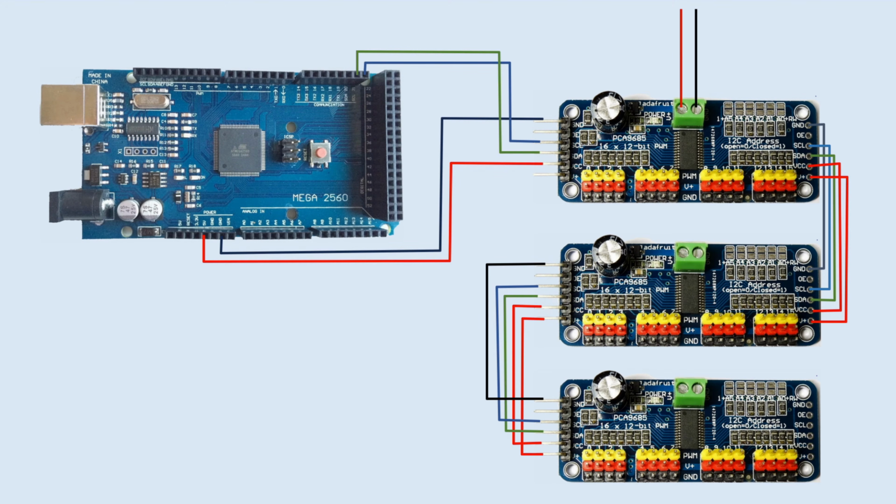All right, as far as setting it up, there's 4 wires that come off of the Mega to control the PCA9685. And you can daisy chain these together and add multiple boards, as we mentioned. Doing so is just a matter of running the wires from one to the next. It doesn't matter what side you go in or out of. The pins on the left and the pins on the right are the same. And you can go in or out in either direction.